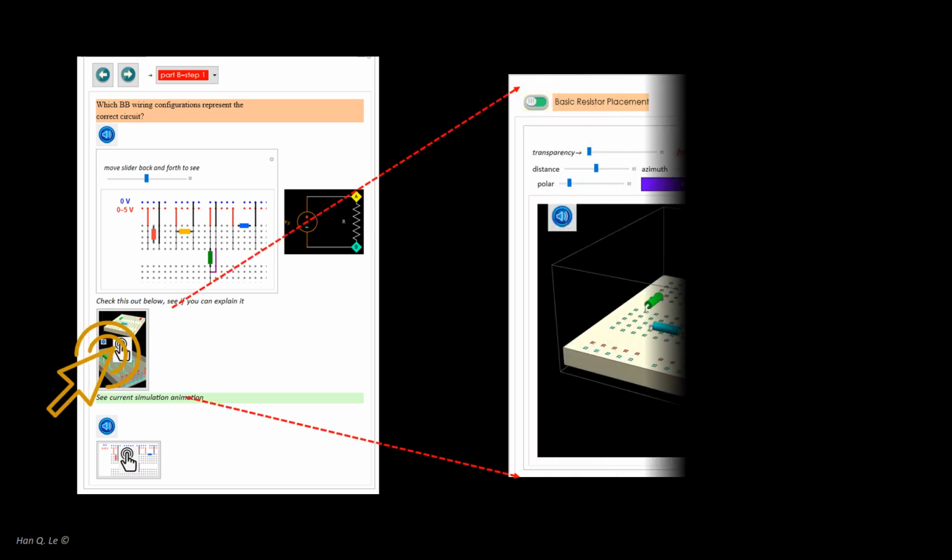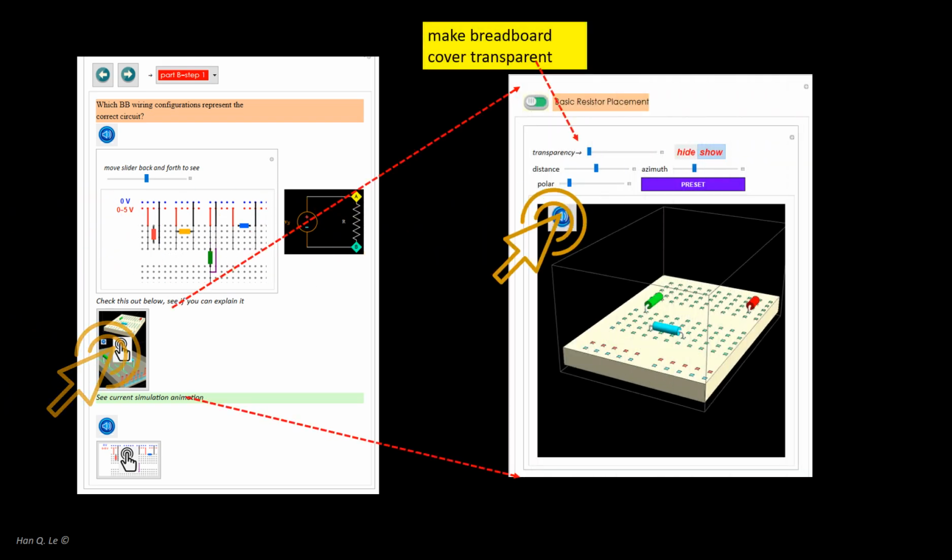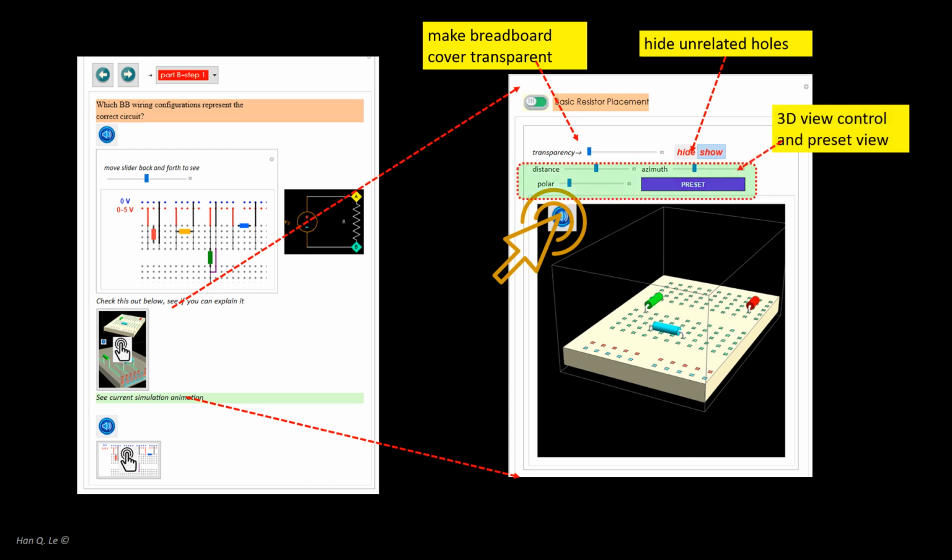If you feel unfamiliar with the previous explanation, try this applet exercise. If both terminals of a passive device are connected together by a conductor, no current will pass through it because electrons will flow through the path of least resistance, which is the conductor. Hence, the device cannot be active. Can you visualize to determine which resistor on this breadboard cannot be used?